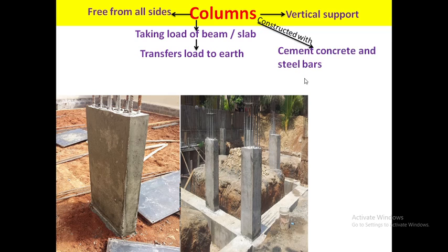In case of multi-storied and frame structure building constructions, the entire load is borne by columns and the floor area or the internal space of a building is freely adjusted according to the requirement. The size, cement concrete ratio and number of steel bars with their diameters are available in structural drawings, which are designed according to the load borne by the column and factor of safety.